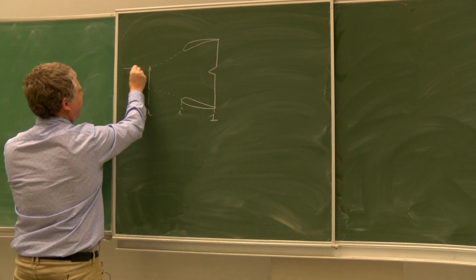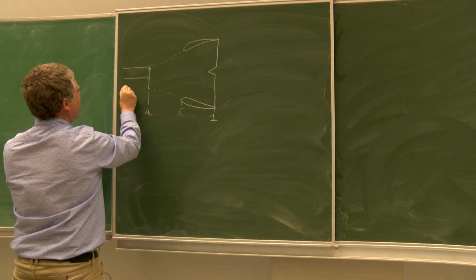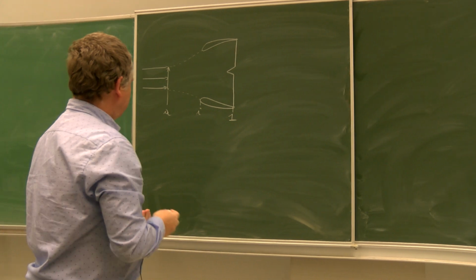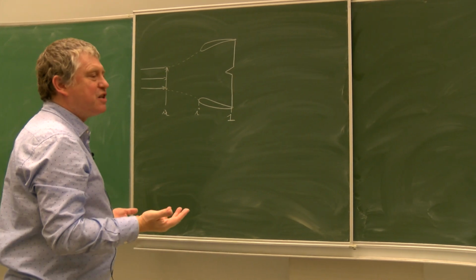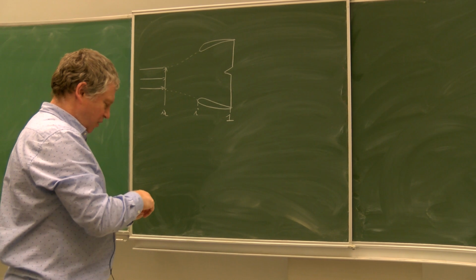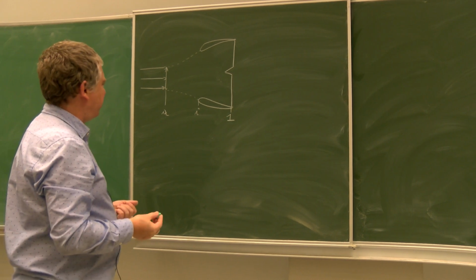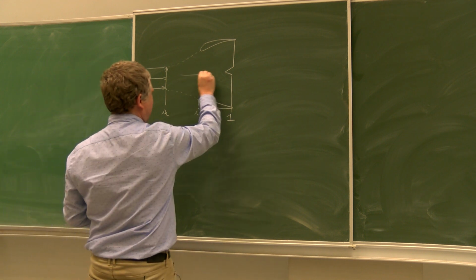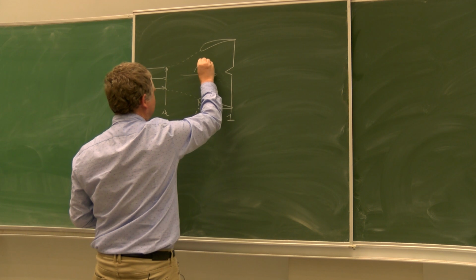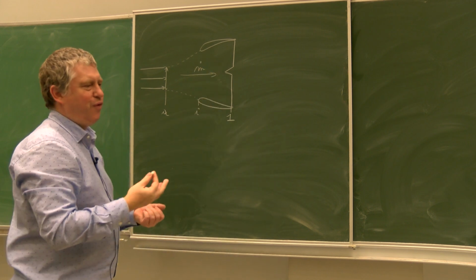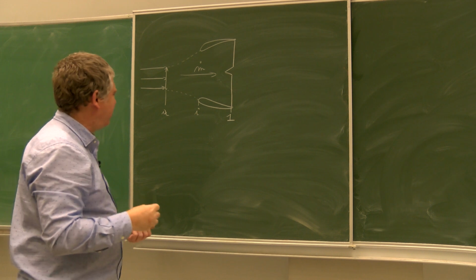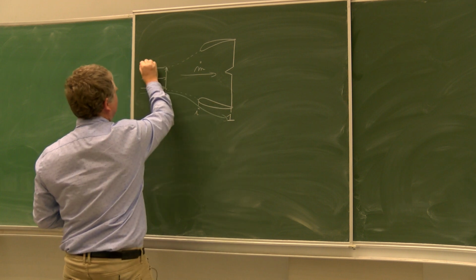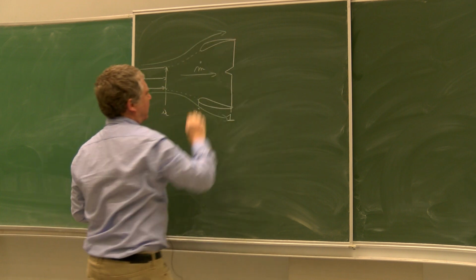Before the section A, we have what we call a parallel flow, an undisturbed flow that only starts to be disturbed from the section A. Of course, there is a certain mass flow rate entering here, and there is also a flow that is not entering into the intake. A flow that is doing something like this, a flow that is doing something like that.